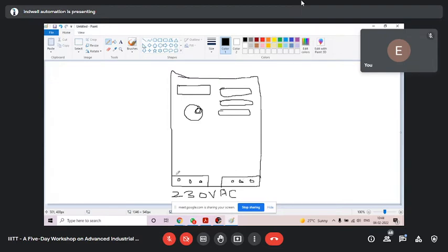So this is the power supply of the AC drive, and this is the output of the AC drive, and here you see this is your RYB. Here only your motor will be connected. As I have shown, I have directly connected my motor to those three terminals. Here I can connect my three-phase motor, as I told that we always use a three-phase motor with an AC drive.